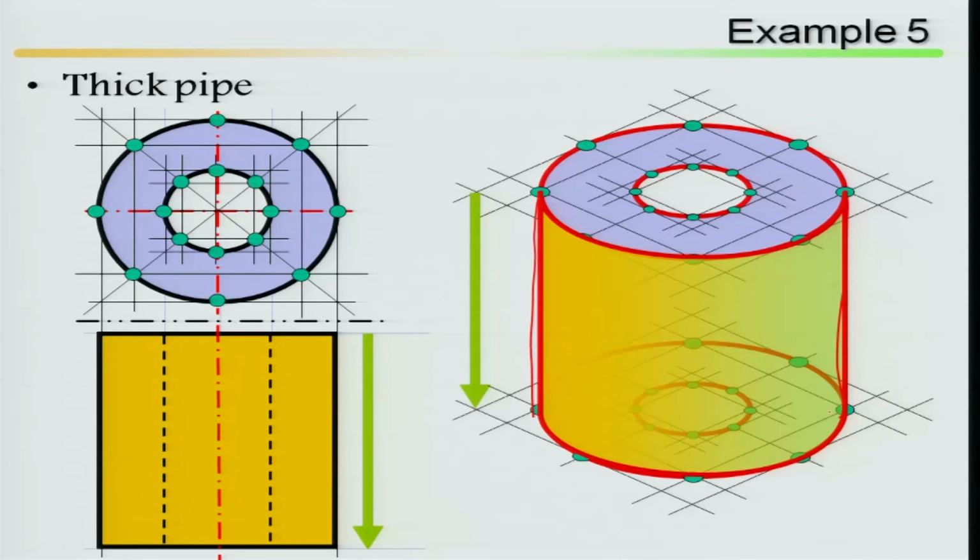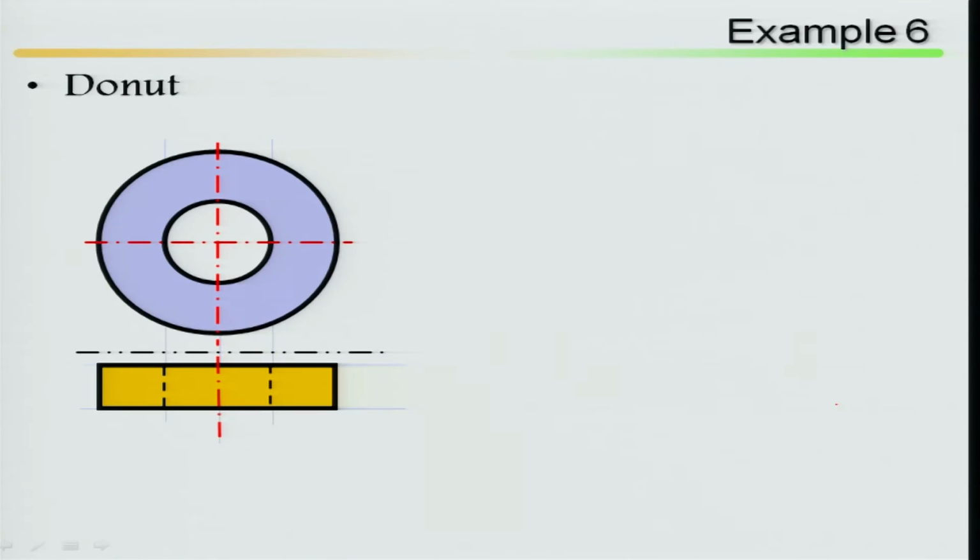You see, if I look at it in this way, I can see the top view. Looking at the front view, these are dotted lines. I cannot see the inside circle throughout; it is a dotted line. That means you erase it in the frontal face and only keep the outer circle. Then you can finish your drawing, and this is your final drawing.